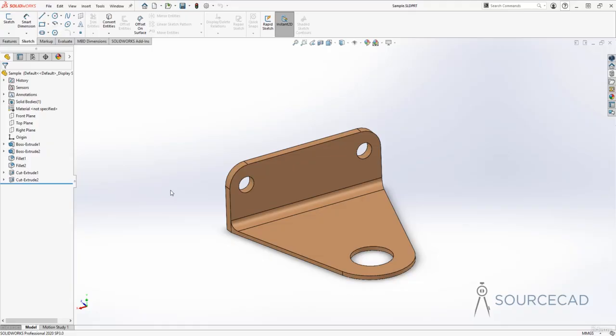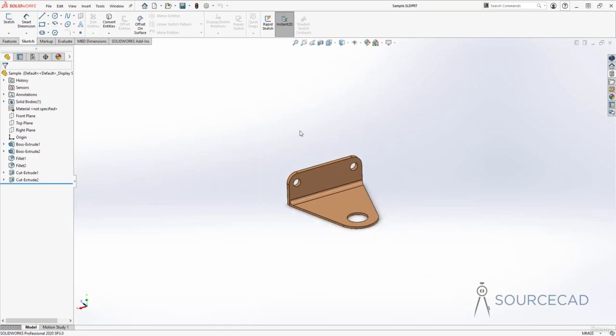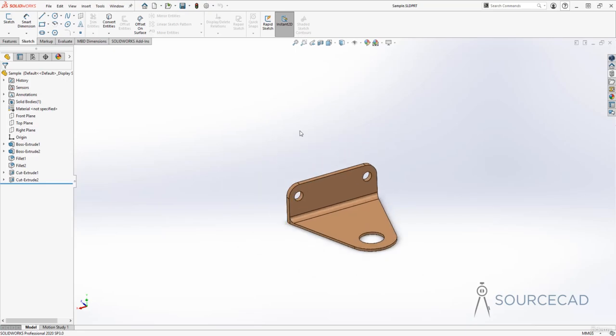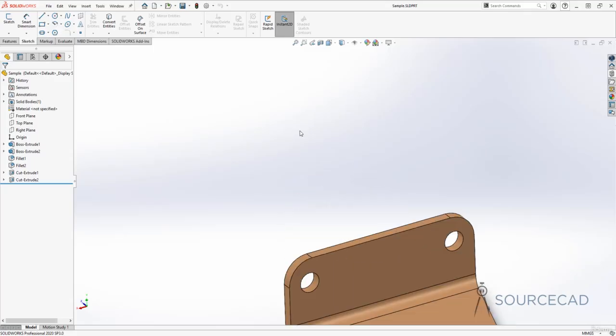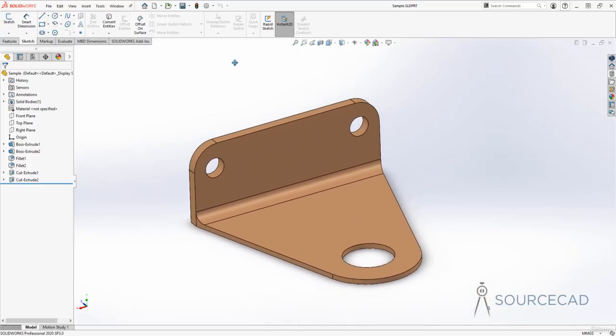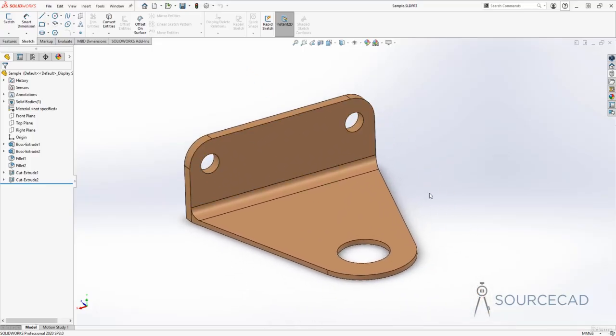Now moving on to this. So I have a 3-button mouse, and here I'll just rotate my mouse wheel. So I'll just rotate it in one direction and it will zoom out. In another, it will zoom in. Now, as you can see, the drawing has moved out of our view area. So I'll press and hold my control key, and then I'll press my middle mouse wheel and I'll bring it here. So that way you can just pan your drawing.